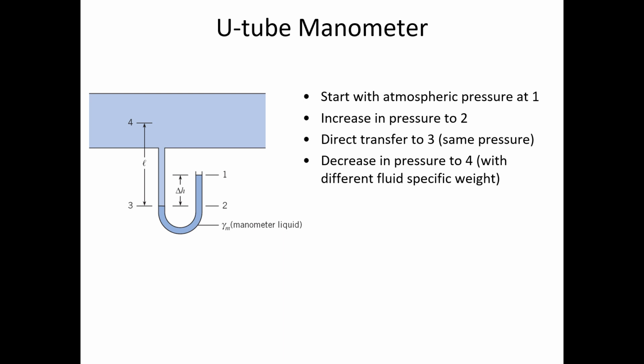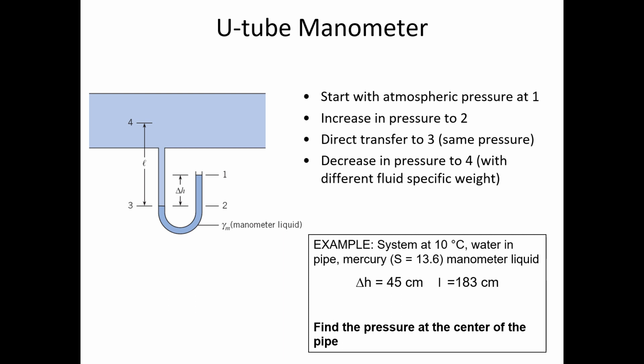And then anytime you're going up through a fluid, you start at what was the last pressure that I knew, at some sort of an interface between different fluids. And as you're going up, the pressure decreases. So just as an illustration, let me give you the calculations on this one.